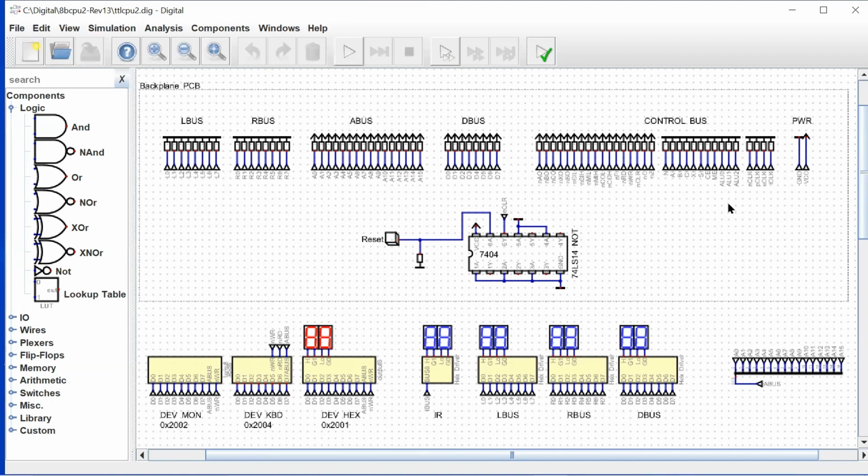And another reason why I came off of the approach of having all of the testing elements on the motherboard was that I would have had to finalize all of the card edge connectors for all of the printed circuit boards now, because we would need the backplane in place to be able to test our individual cards.